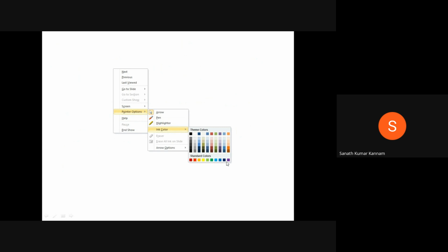Next, you see, equivalency of gates. What is this equivalency of gates? Equivalency of gates is nothing but, suppose we discuss Boolean algebra, I think you have an idea about De Morgan's law. So what is De Morgan's law? Like A or B, whole bar, equal to what? A bar and B bar.